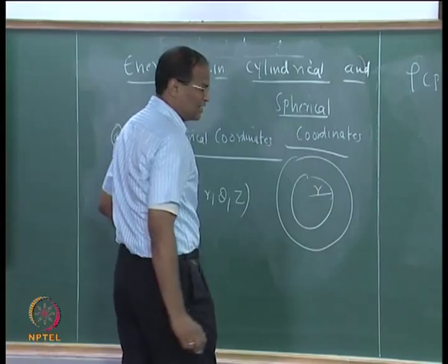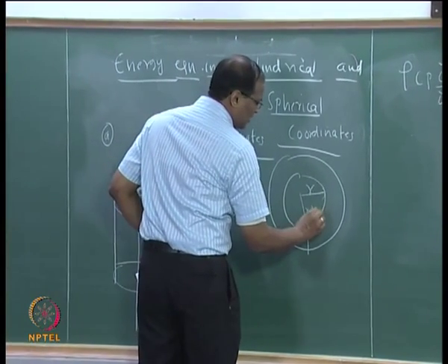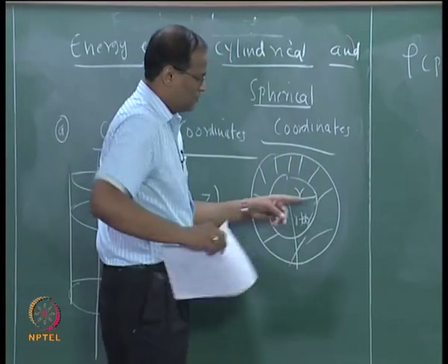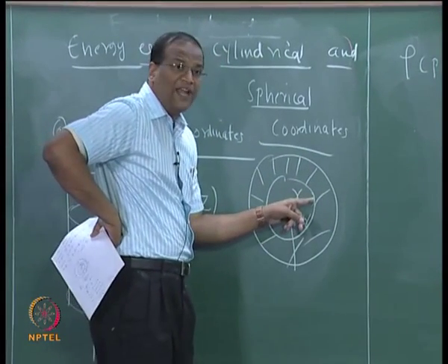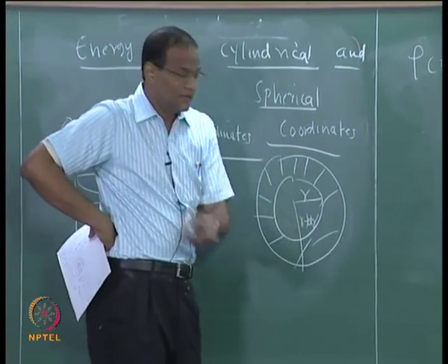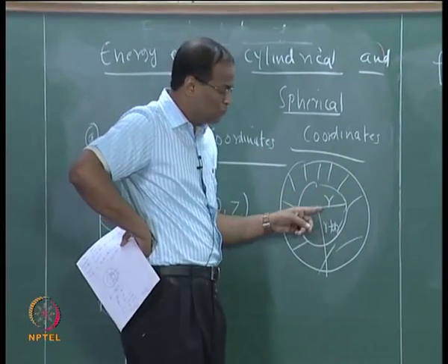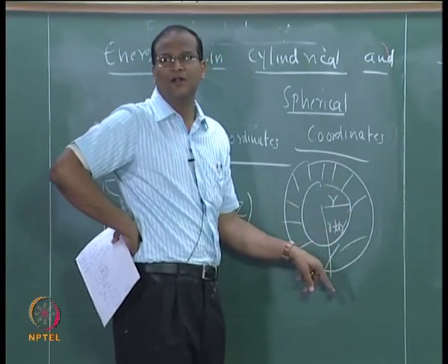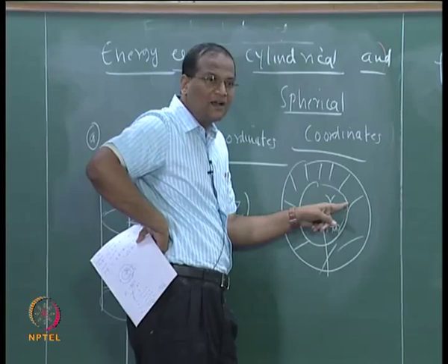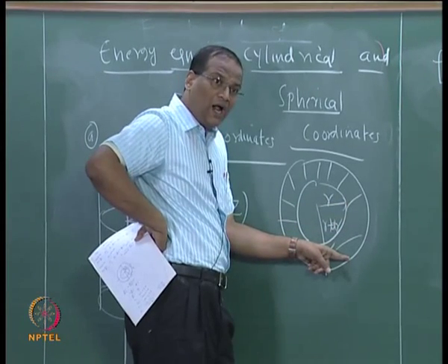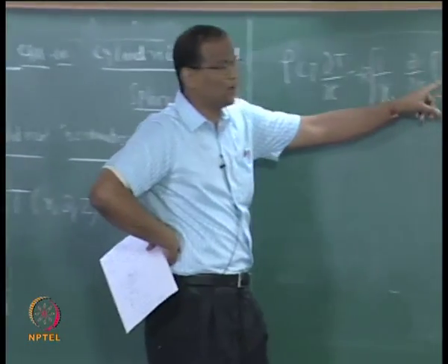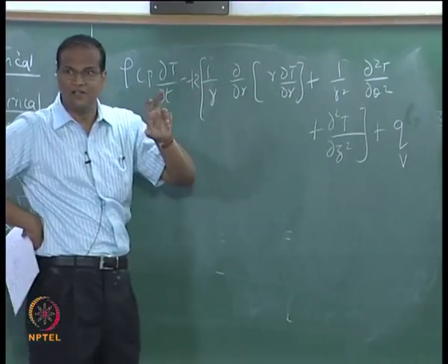is basically, if you take a section r, if you take a section r plus dr, there we put minus small q at x is equal to minus small q at x plus dx. Here you can't put that, you have to put minus capital QR equal to, because capital QR is small qr into 2 pi r dr, 2 pi r plus dr. So that is why the dou by dou r of r dT by dr is coming, the area continuously changes.